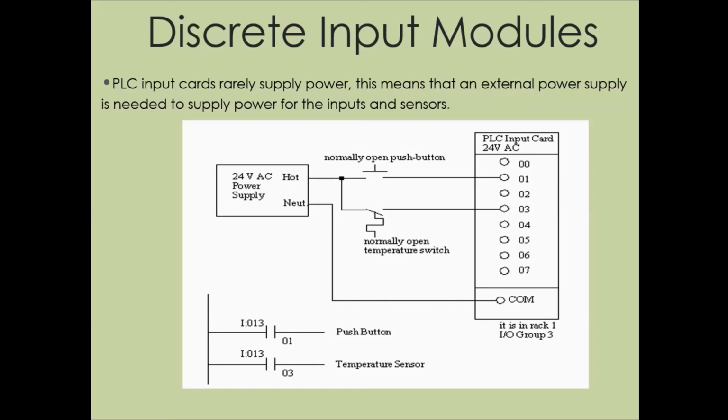PLC input cards rarely supply power. This means that an external power supply is needed to supply power for the inputs and the sensors. We can see here we have an external supply. It's a 24 volt AC power supply. We have a hot and our neutral.